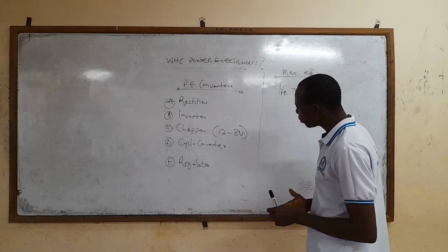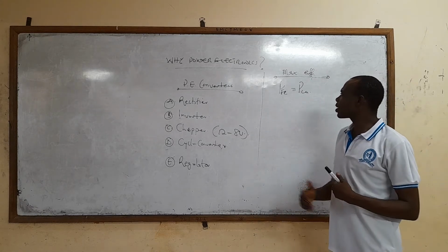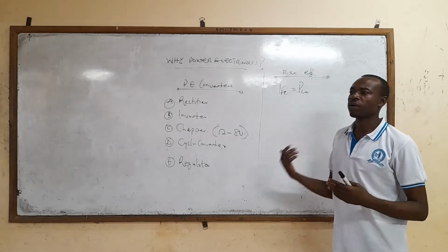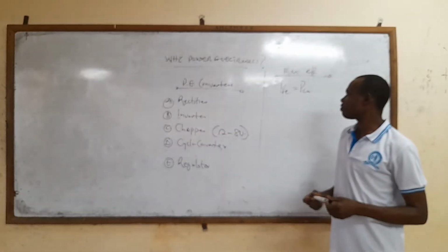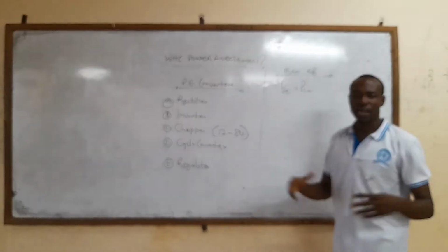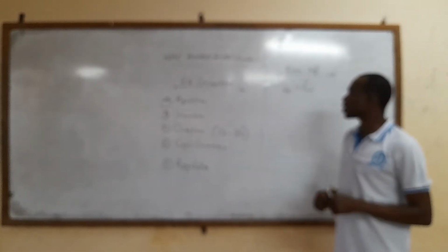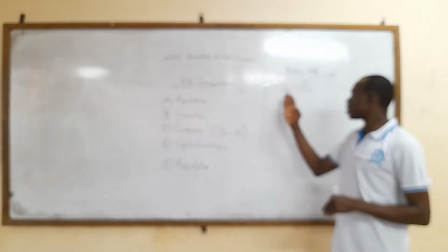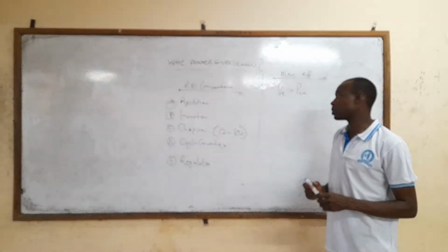Now, let's come to how a transformer works, or what are some of the requirements of a transformer working effectively or efficiently. We all established in machines that before a transformer can give us the optimal efficiency, this condition has to be met: iron loss should always be equal to copper loss before we can have maximum efficiency.